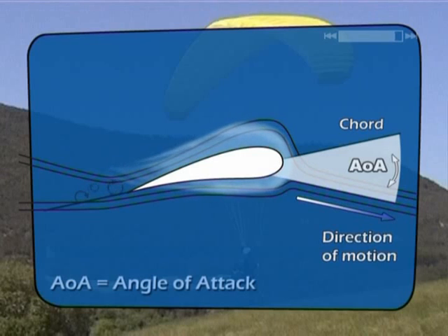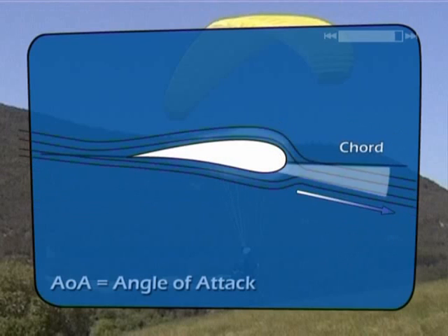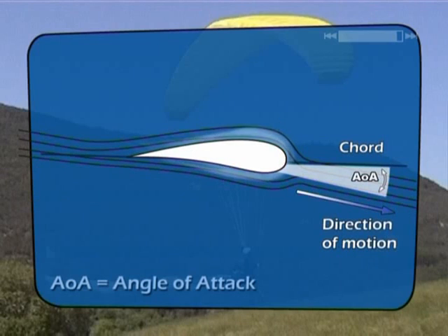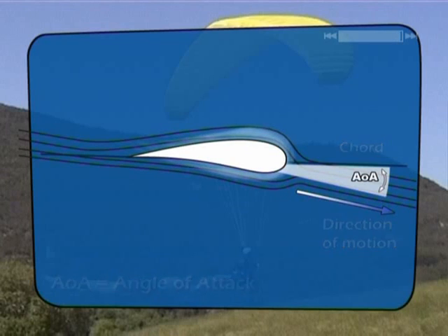The angle of attack can be decreased using the accelerator system. As the angle decreases, drag is reduced and the speed increases. The glider continues to accelerate until a new equilibrium is found. The wing then stabilizes at this new speed and sink rate. At low angles of attack, paragliders are more prone to collapse. This is why you should not use the speed system when close to the ground or flying in turbulent air.